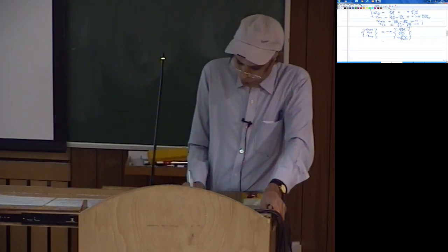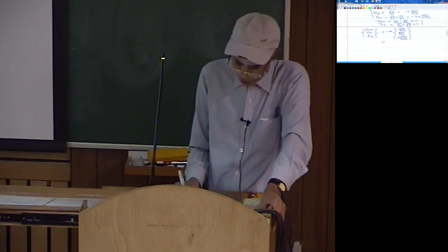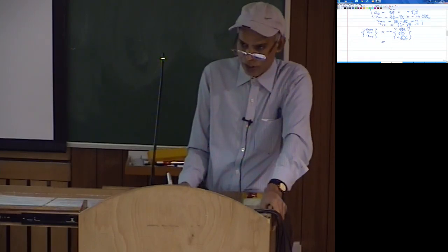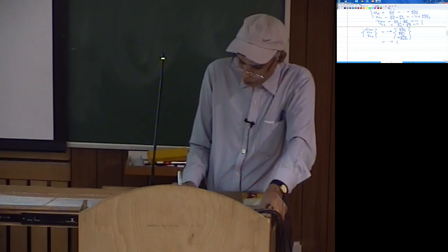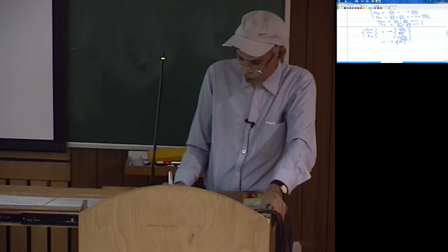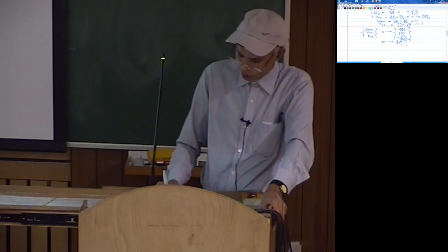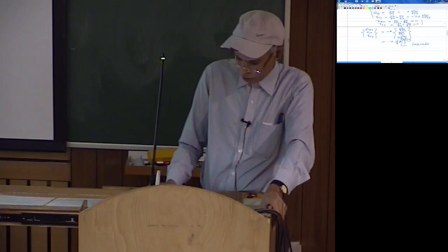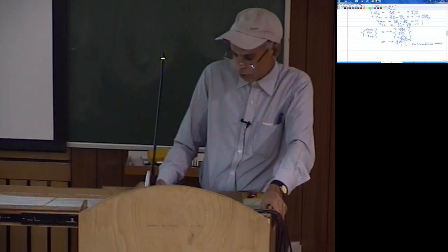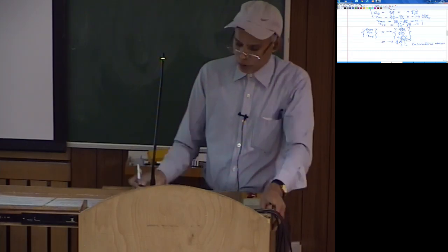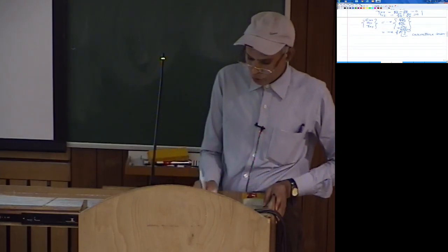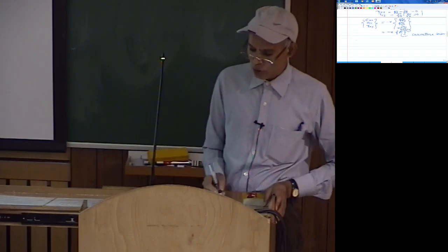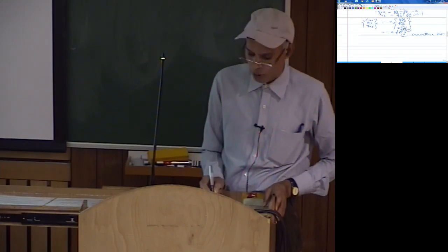And in this plate theory, we call this a curvature tensor. So minus z into, sometimes we simply write this as curvature tensor kappa, where kappa is known as the curvature tensor. And of course here it is written in vector form. So this is your strain, the independent components of strain written in terms of minus z into kappa.